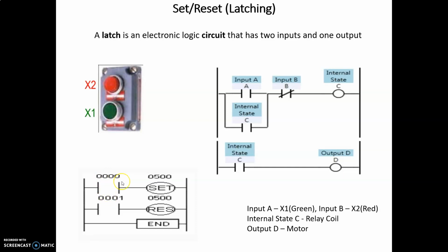So one input is used to switch on this output, which is called set. Similarly, if you use another input to reset it, meaning to bring it to the initial position, the off condition, that is called reset. So it is called RES. In this case, to have the simple operation of off and on, we will have to use two inputs, set and reset. So this example is actually quite useful in our cases.